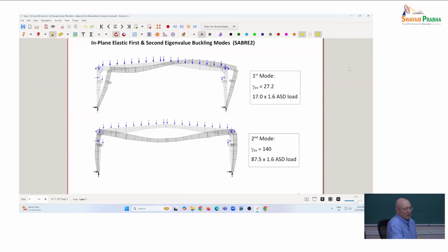And we didn't talk a whole lot about the buckling sensitivity analysis, although we had that selected in what we worked before. What the buckling sensitivity analysis tells you is you look at mode 1 for this, and it tells you, hey, your columns are what need to be designed here for mode 1. And then it tells you, yeah, the girders aren't doing much here in mode 1. I'm going to let Balint explain some of that in more detail next week.